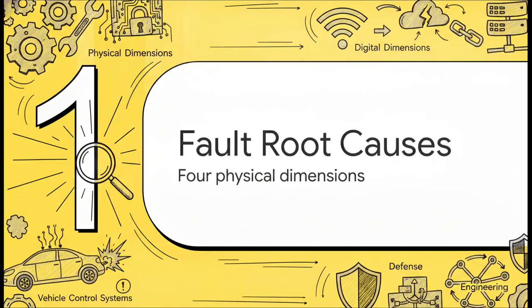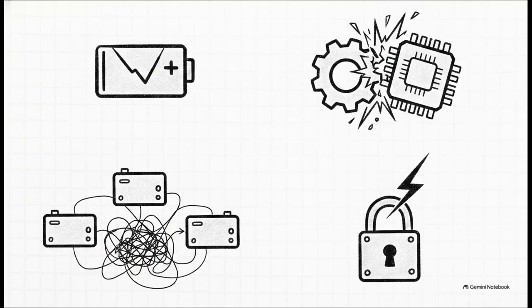Section 1. Firmware fault root causes. To build a solid defense, we kind of need to understand the enemy first, right? So let's look at the four main culprits that can trigger a U0311 fault and totally compromise a multi-core vehicle control system. First up, we've got low-voltage power sags, basically brownouts that happen during firmware flashing. Second is a hardware-software mismatch. Let's say a technician replaces a motor, but totally skips the commutation offset learning step. The system might miscalculate angles by, say, 45 degrees, inducing a massive power surge that literally melts the silicon carbide power modules in a fraction of a second.